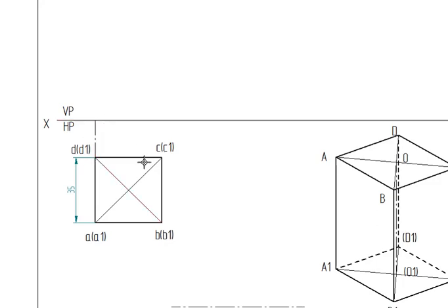Start it, end it here, see this point till here. Here I'll be able to see the O point, small letter o. This is the actual object, where we kept everything in capital letters. These are the projections of this, so this should be a thin line. This one, O1, is not seen.